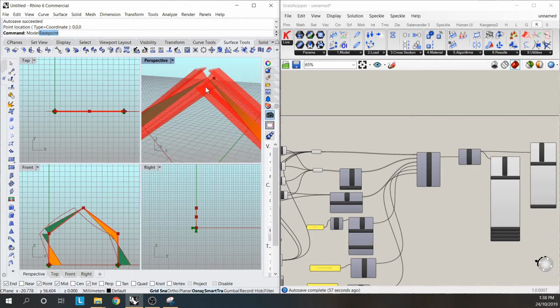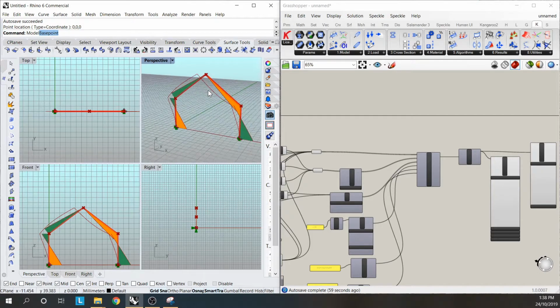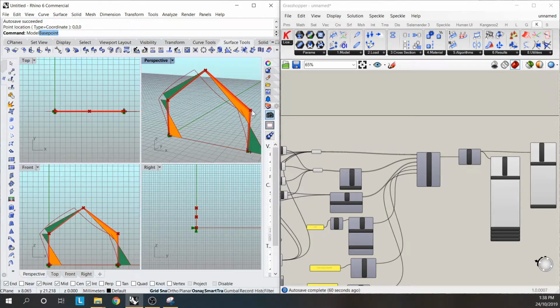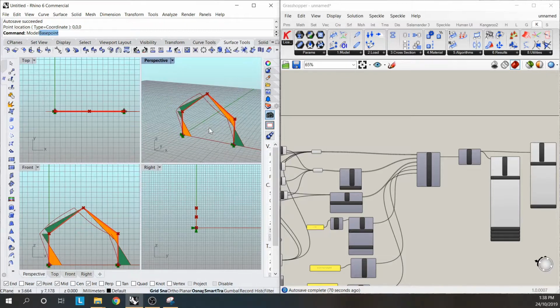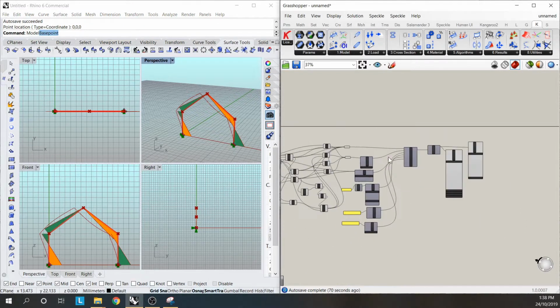It's interesting that the moment is 0 here, but that will actually be the case because it's completely mirrored, you're loading up both sides of the portal frame, and all the reaction will end up coming out at the base of 2 frames effectively. So that is actually correct.